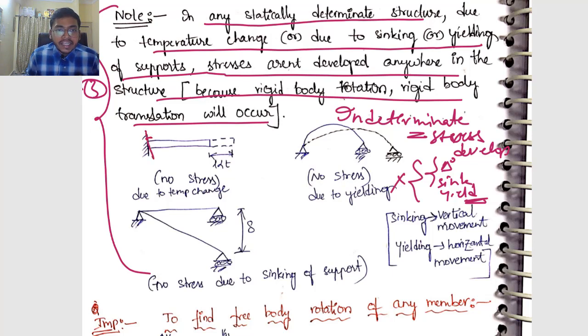Because if you are taking a statically determinate structure, let us take a cantilever beam like this. You apply the temperature, obviously it will get elongated, so there is no reaction, it is free to expand, right? So no stresses are developed in this body, it is just expanding.